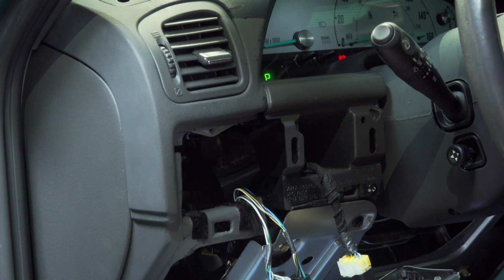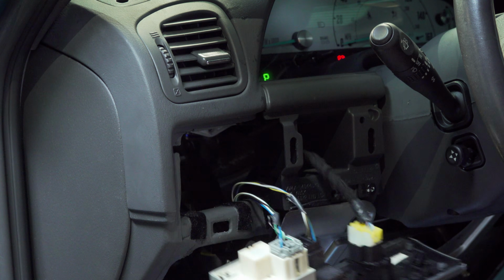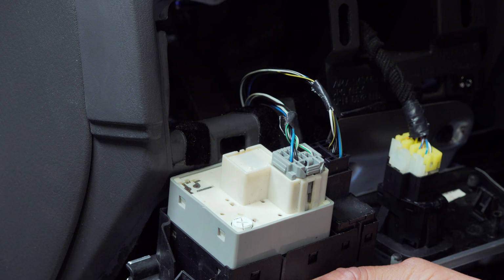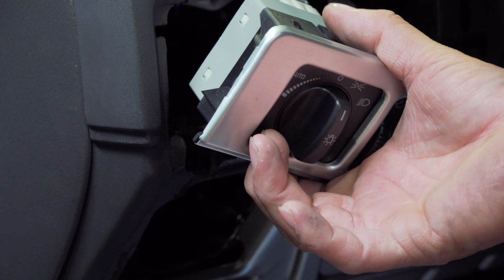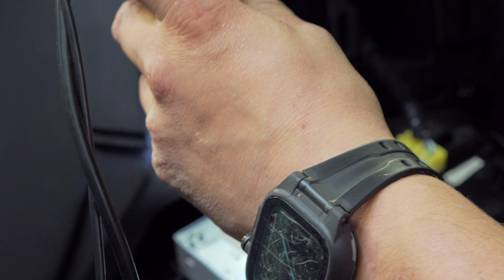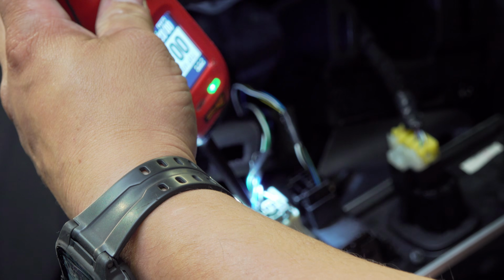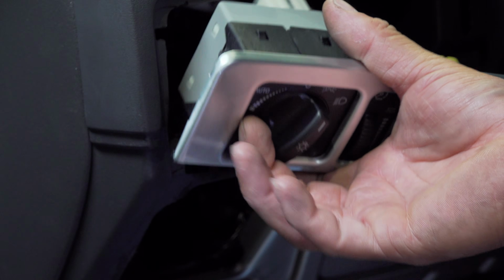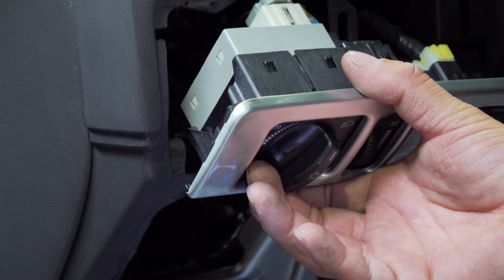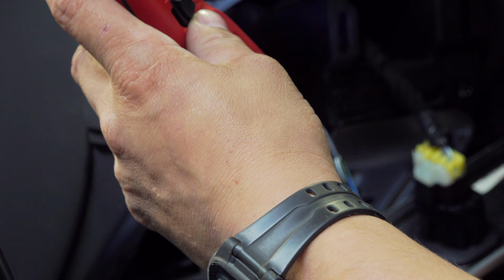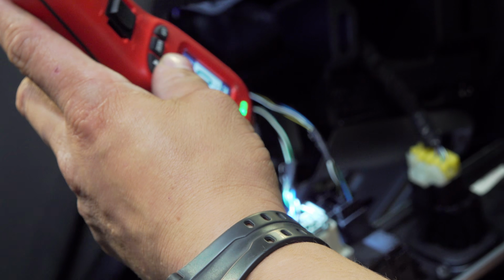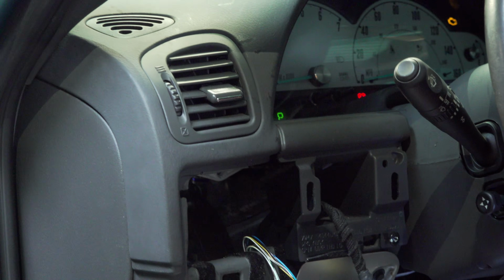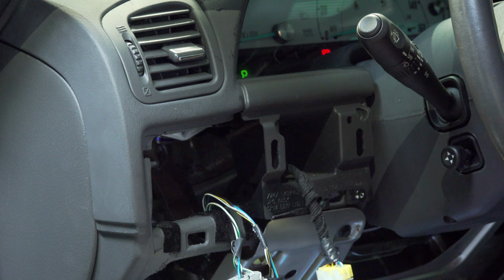So I've got my power probe already ready. Oh, you guys can't even see this, I'm sorry. You can really take a good look at this. And I'm going to have it on the off position right now. I'm going to take a look, and we have a good ground. When I hit the dimmer, we have it on park. My cluster already dimmed a little. It is still ground. And so that you guys can see everything, we're going to try to give it power and see what happens.